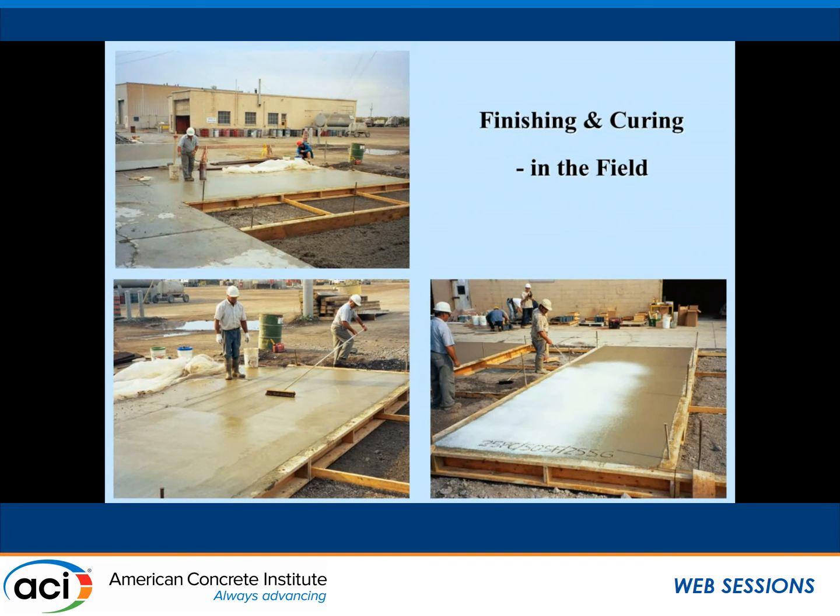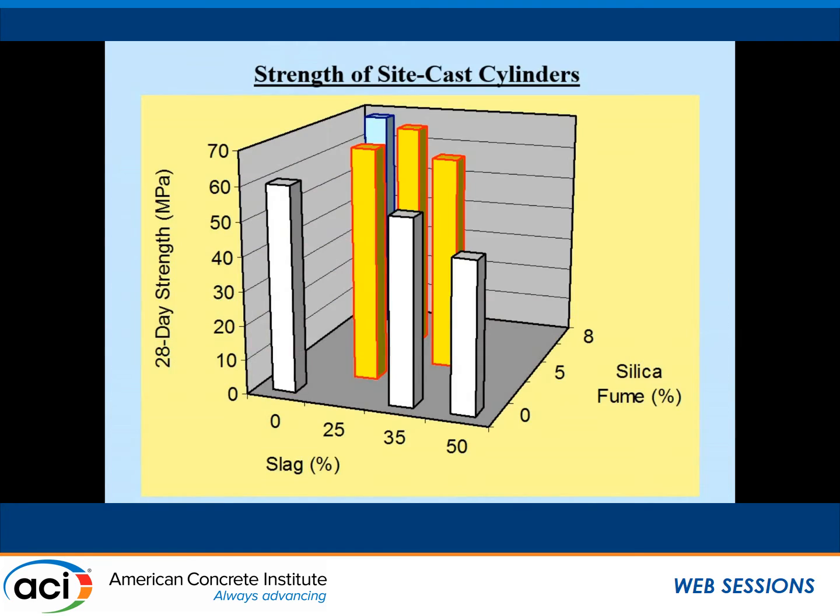And I think you can see here the curing compound being applied really nicely, nice and uniformly. The one thing I learned about this site is the most important piece of equipment to have on site to ensure quality control is a video camera. If a contractor knows he's being videoed, he'll do everything correctly. So we have really nice application of the curing membrane there.